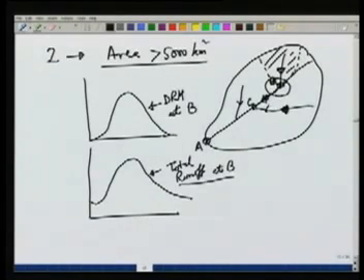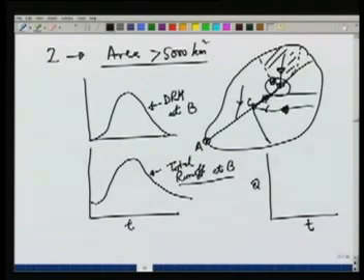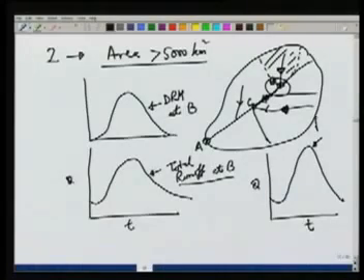Similarly, we can apply the unit hydrograph theory for the catchment area at point C and obtain total runoff at C, which of course will be quite different from that at point B, because the catchment area may be larger, it may have different slope, different properties. So this is runoff at C.